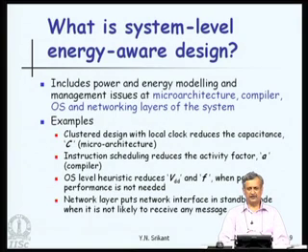So, what an instruction scheduler in a compiler can do is rearrange instructions, so that a function unit which is busy keeps on doing work, that is, it keeps on executing instructions, and a function unit which is idle remains idle as long as possible. In other words, by rearranging instructions, we try to increase the busy periods and also the idle periods of function units. So, we reduce the number of transitions from high to low and low to high, thereby saving energy and power.